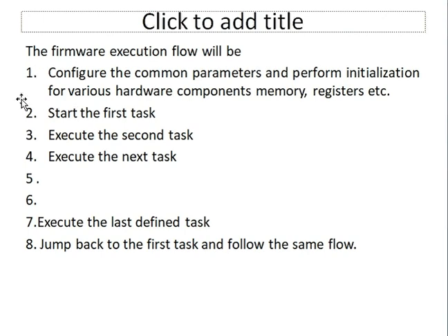You are not going back to one, because configuring is done at the first instance itself. If you remember Arduino code, you remember inside void setup we expect the instructions written inside void setup to be run once, because there we will be configuring, and in the setup loop we will address which pin we will be using and what is its mode, is it input or is it output.